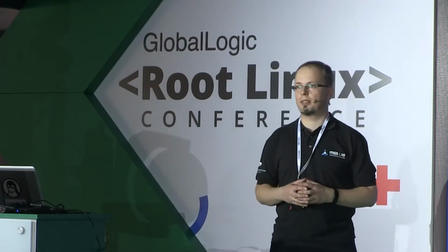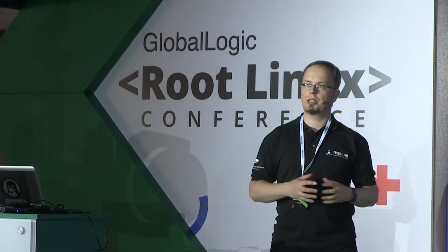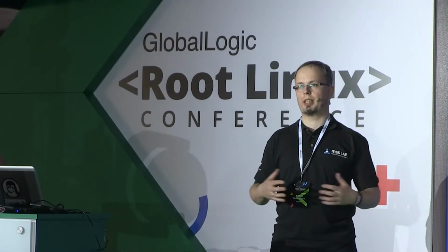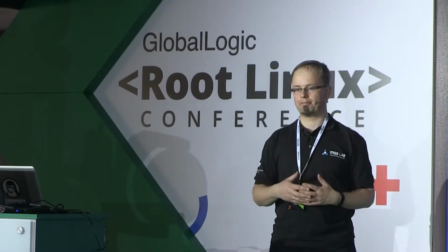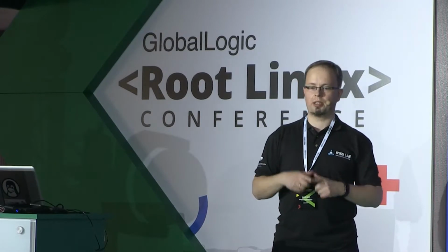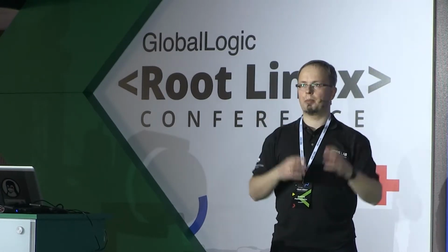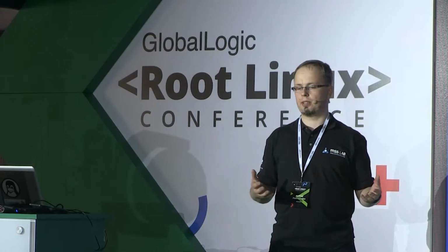Enter FunctionFS. What is FunctionFS? It is a very special USB function, and as a USB function, it can be used as a component of a gadget composed with configfs. This function is very special because it actually delegates the implementation to user space through a dedicated virtual file system.